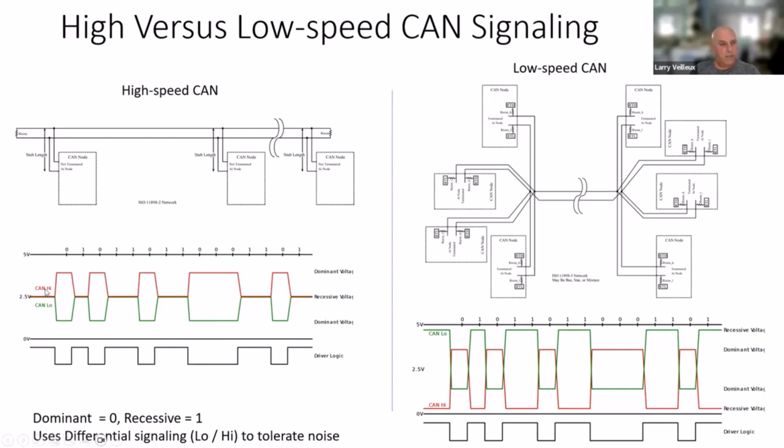Now, let's look at the actual voltages. These are the signals, and this is where the CAN high, CAN low, with high-speed CAN, the medium voltage is 2.5, the maximum is 3.5, and the low is 1.5. When you're at the medium level, which, by the way, the voltage is held there when nothing is happening. They call it recessive state, which is actually a logical 1. You can see up here, 1 is when both the CAN high and CAN low are in their recessive state. They're both holding their respective lines. Remember, these are two separate wires at 2.5 volts.